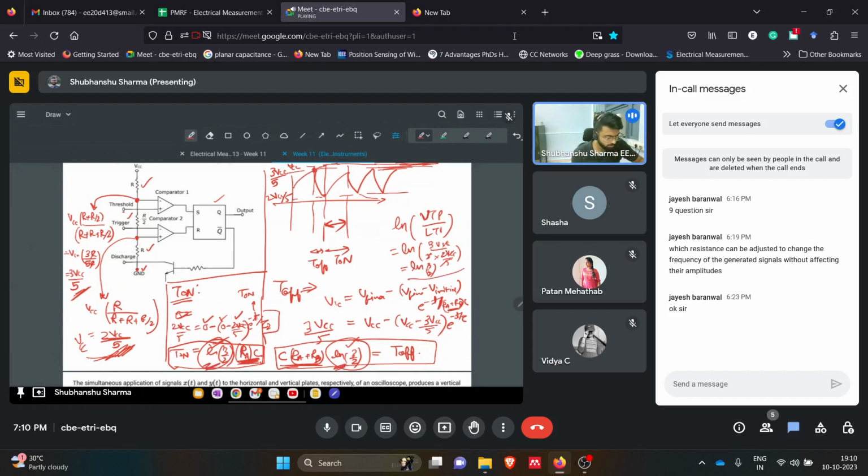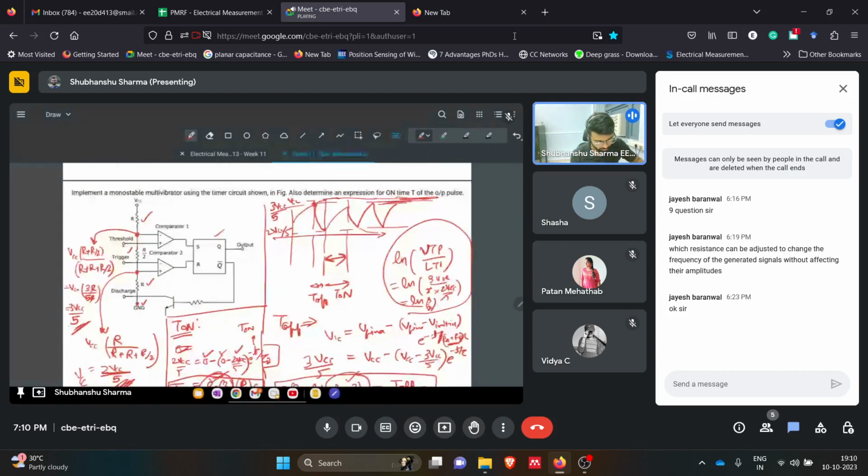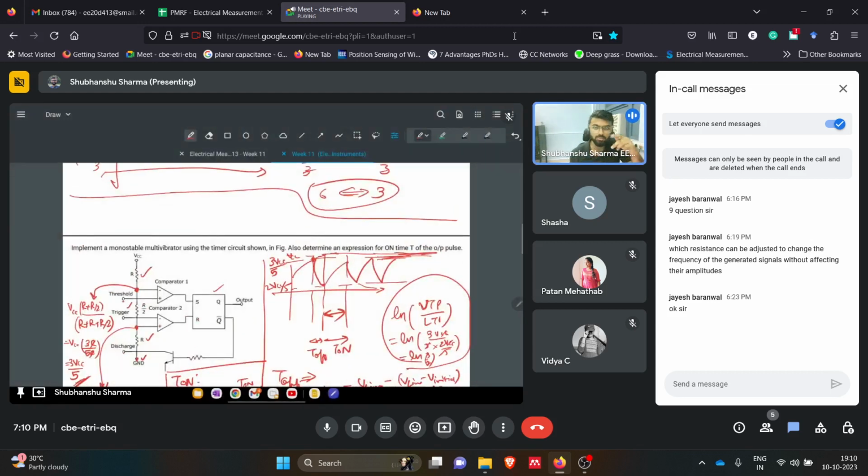Just to be sure, what were the upper and lower threshold voltages in that earlier case, which you have been told in the lectures? That was 2 VCC by 5 and VCC by 5. Yeah, it's making sense.